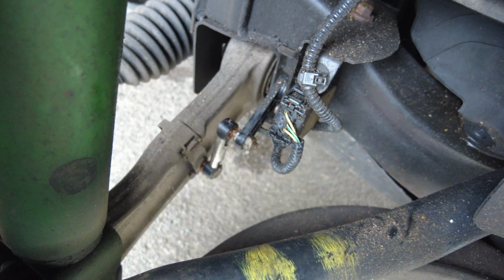And once we've got the wheel refitted, we'll get out the Jaguar IDS diagnostic system and we'll look to recalibrate the front axle sensor now that it's connected to the suspension arm, so we should get some readings and then we should be good.